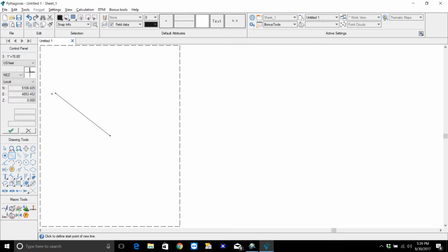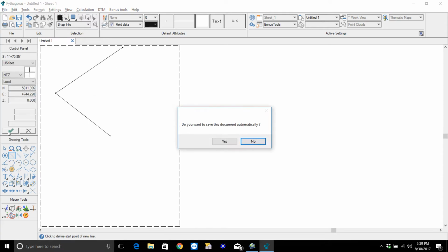As I get near this end point, left click once, just drag it away, put it anywhere out here, put it down. Now move your hand away from the mouse to the tab key over here. Now let's just say that the real distance here was 205.75. I hit the tab key again, and I'm currently at a bearing of north 65°55'17" east. Let's change that. Let's make that north 55°45'50" east. So that's the bearing that I've pulled off my legal description. And when I hit the green checkbox, watch what happens to the line. See it move?